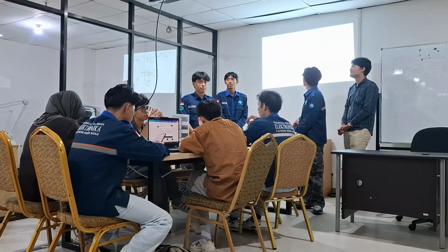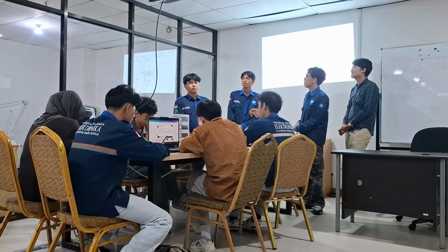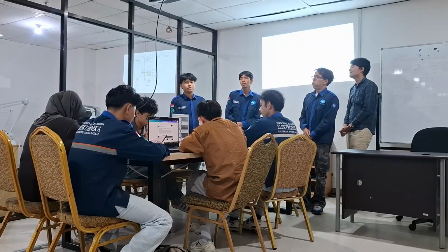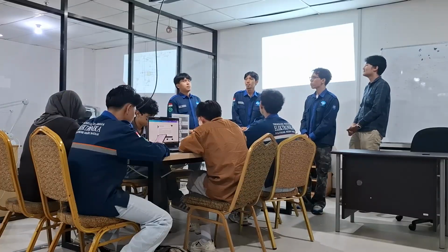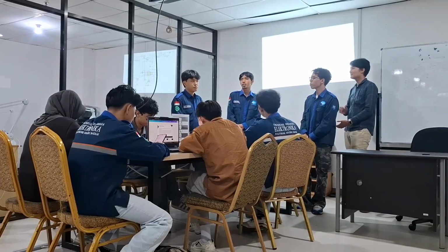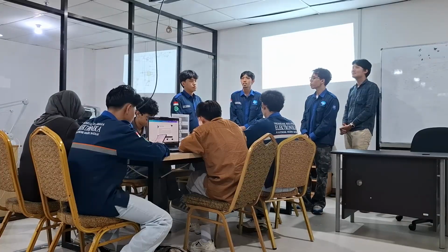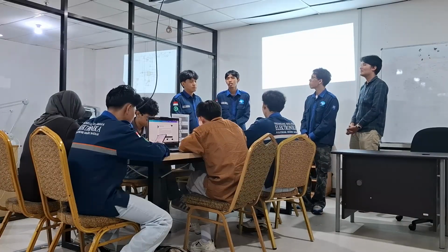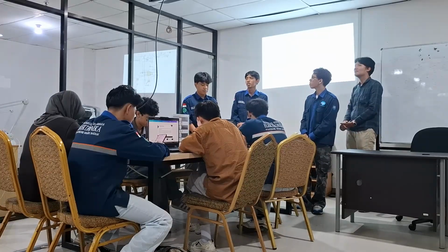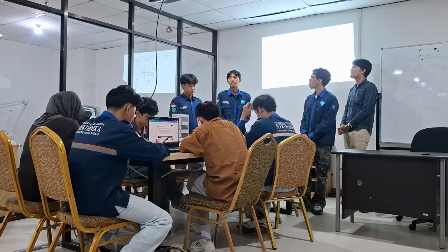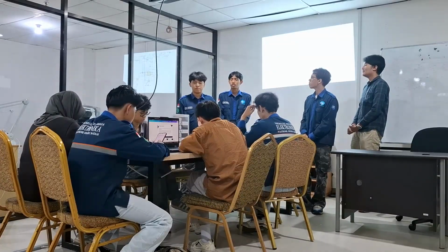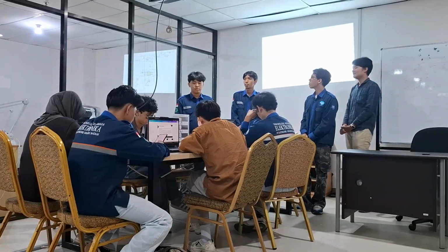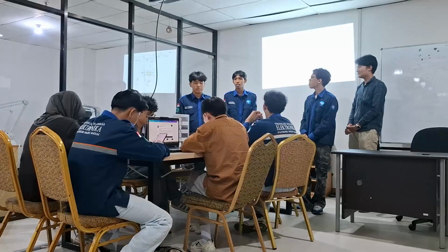But when the switching is off, the energy in the magnetic field is released to the secondary side, so that the energy goes to the load. This rapid cycle continues at very high speed, so it provides a stable and efficient power supply to the load. I think it's for me.